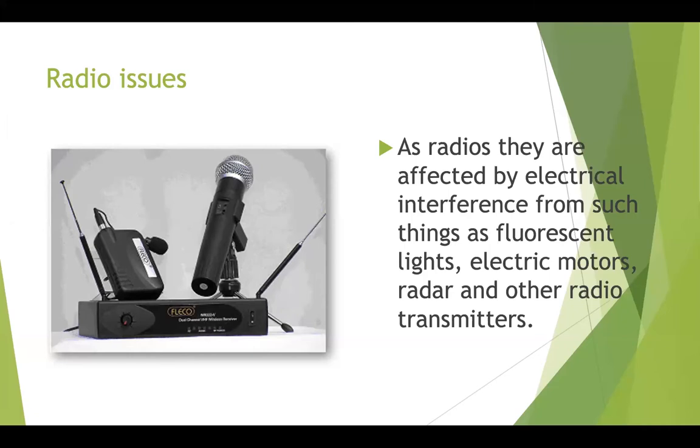Other radio transmitters: if you're near a strong radio source, if you're at the airport, a good example, a lot of television news people know that as you get closer to the airport with their giant radar domes for navigation, RF can be interfered with very badly, right? So keep that in mind. It's not a reason not to use it. It's just something to be aware of.